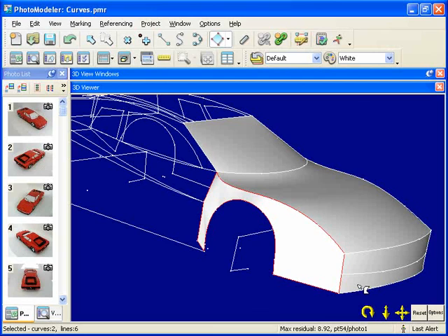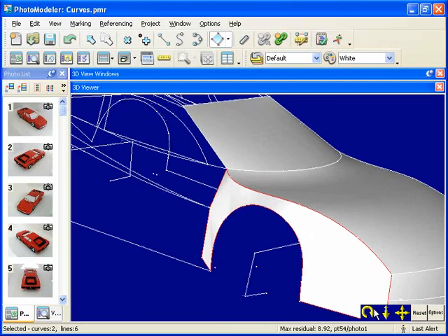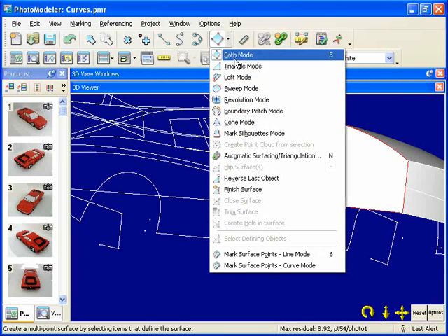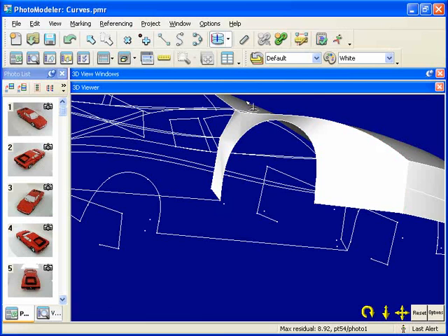Lastly, we'll show the surface of revolution. We'll do the wheels. The wheels were marked with a small line from target dots, and the axle was from 2 other marked and referenced points. We pick the revolution tool. Pick our profile curve and our axes of revolution. Similarly, for the front of the wheel, the profile curve and the axes. We have our completed wheel.